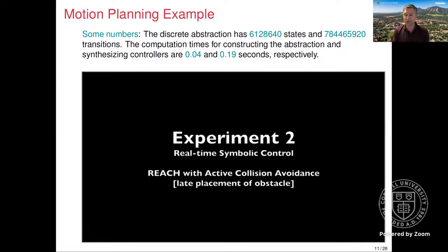Like you want to design a controller for a switched system, let's say achieving practical stability. You might say, why practical stability? Because I can actually write a linear temporal logic formula for practical stability. Practical stability says reach some region around the equilibrium point and stay there forever, right? That's a reach and stay problem. So the way we are able to handle switched systems, we have an extra constraint over the switching signal, namely a dwell time condition, right? And because now when I build a finite representation of my dynamics, it's very easy for me to add this extra logic for the switching signal, because I can incorporate memory, right?